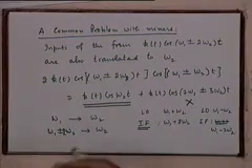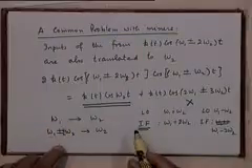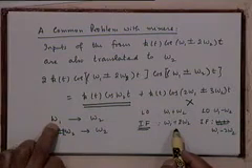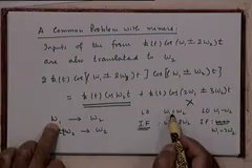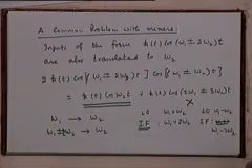And therefore, if both the signals were simultaneously present, the signal at omega 1 and the signal at omega 1 plus 2 omega 2, and we have used a local oscillator of this frequency, the band pass filter output will contain components corresponding to both of them, right? And there will be a crosstalk. You will get the sum of two signals. Is that clear?